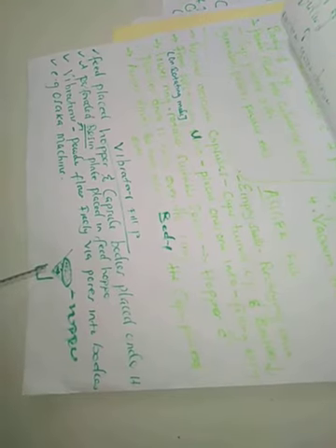So the hopper is fitted with a resin plate which is perforated, and your powder is going to be on top of the resin plate. This resin plate is made in such a way that it can vibrate. As it vibrates, it facilitates the movement of your powder through these pores, then into these capsules. These are predetermined volumes that enter the bodies.